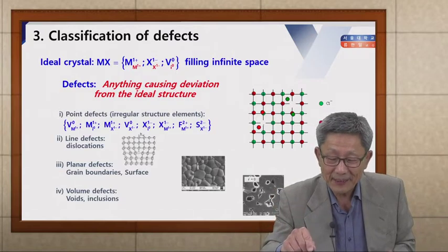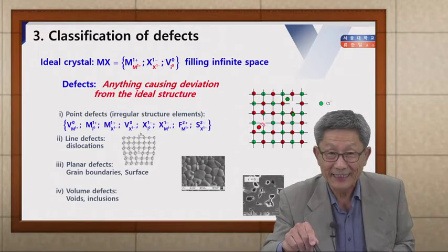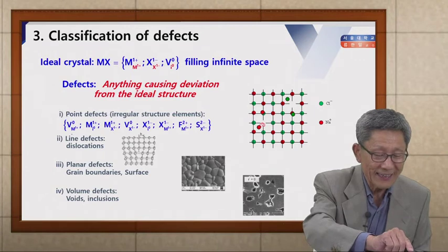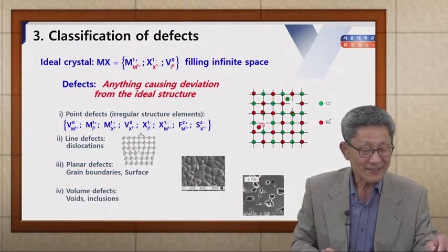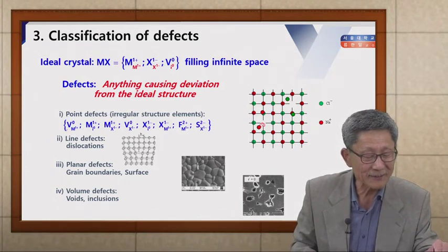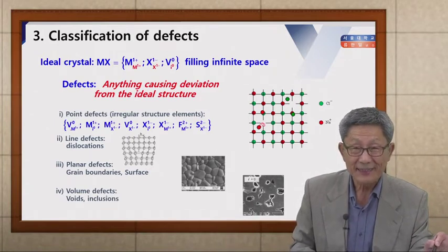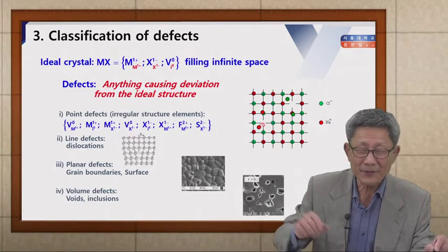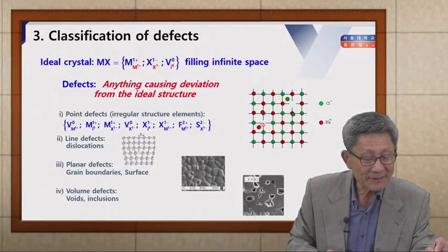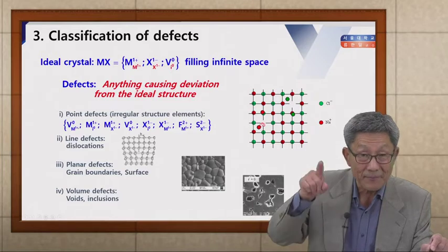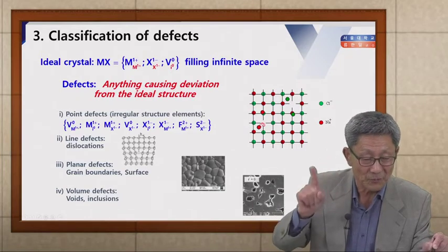Now there used to be a cation here, but now this cation is missing. So this is a missing cation. A missing cation is represented here by a vacancy V. Its actual charge is just 0 because there is nothing. But this vacancy is now sitting on the cation site, which should have a positive one charge.